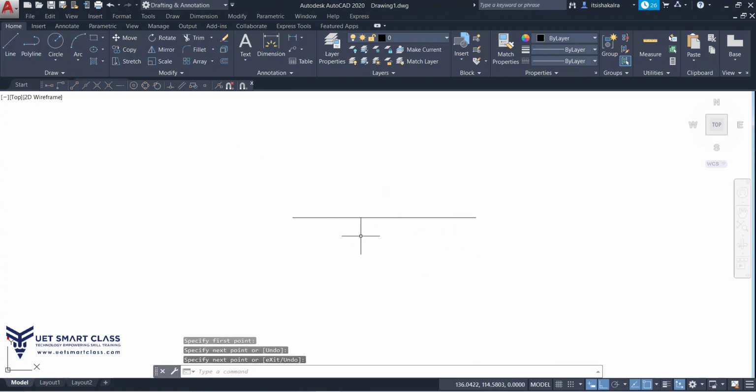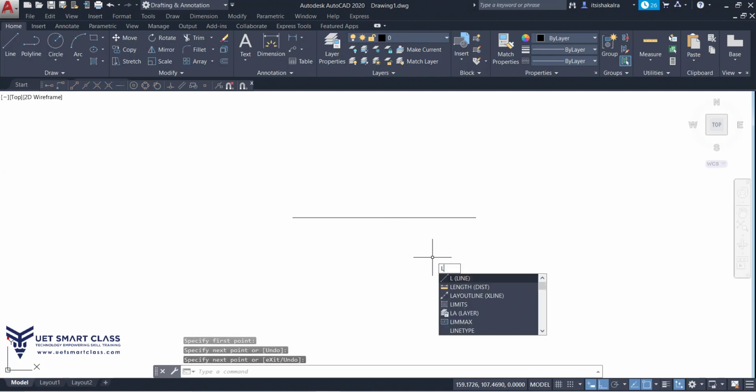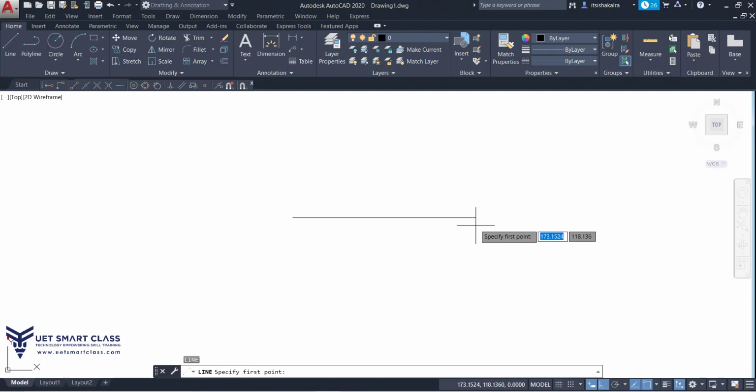All right. Now, when I start drawing my second line, see, this is what the marker is about. When I go near the first drawn line, this marker appears in front of me. As a square, this is the endpoint. So when I put my cursor here for a few seconds, see, the tooltip is showing me Endpoint. This is a midpoint. This is an endpoint. All right. This is what I was talking about.